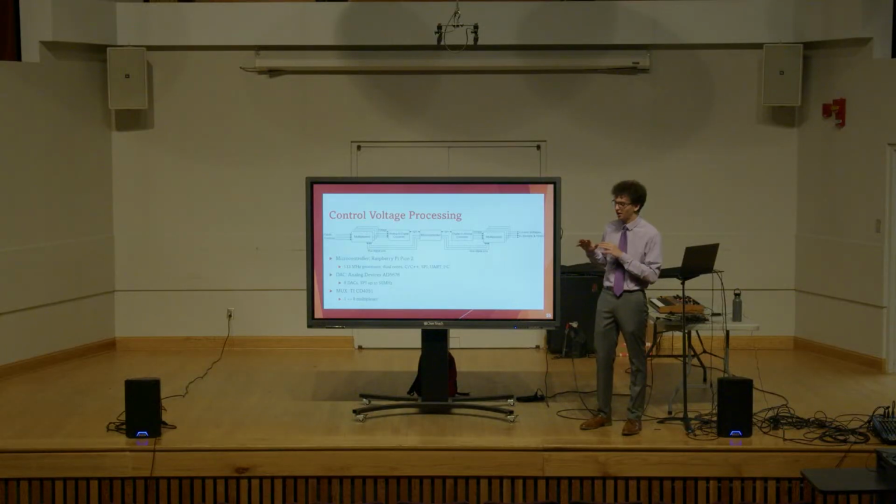And so the tools that I've chosen to implement this with are the Raspberry Pi Pico 2 for my microcontroller, and I've chosen that because it's extremely fast, powerful, and inexpensive. It has multiple cores, which is great, which means I can run 2 different pieces of code at the same time.